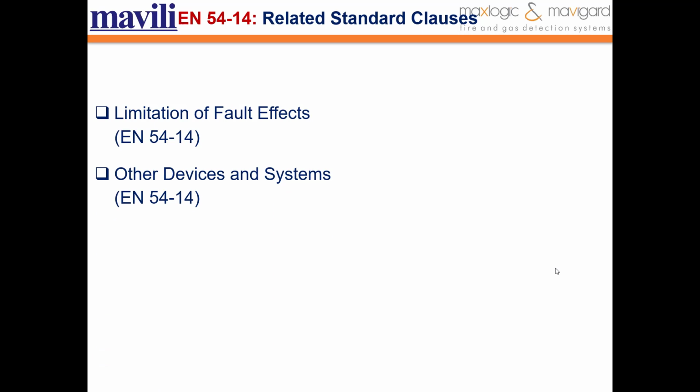Other devices and systems. In addition to the main purpose of detection and alarm, signals from the system can be used to trigger auxiliary devices directly or indirectly, such as fire extinguishing equipment, smoke or fire doors, smoke ventilation equipment, smoke or fire dampers, shutting off ventilation, elevator control, and safety doors. Operation or malfunction of an auxiliary device should not compromise the operation of the fire detection system or prevent it from signaling other auxiliary devices.